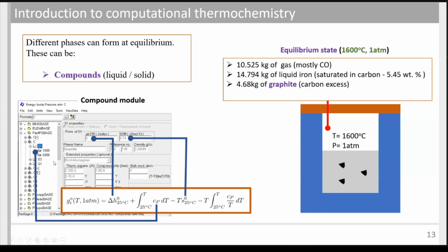And you see here that the ingredients that we need to define the energetic behavior of this phase are the following. We need the enthalpy of formation at 298. We need the S at 298, which is obtained from the integral of the Cp, and we need the Cp expression. You saw this morning that there are many strategies to estimate the Cp from simple mixing rules.